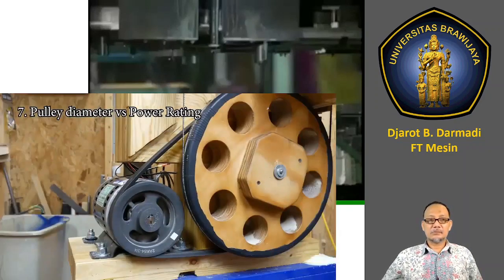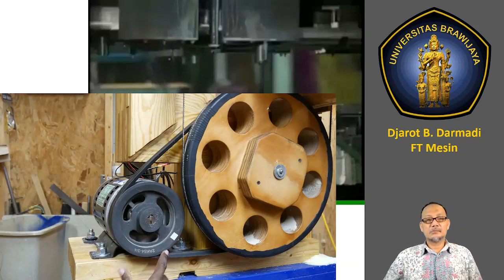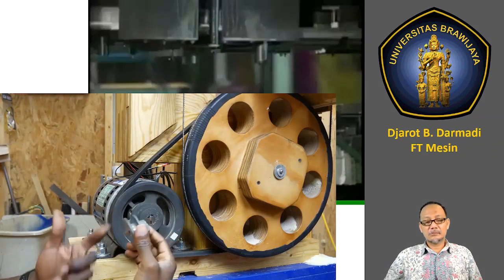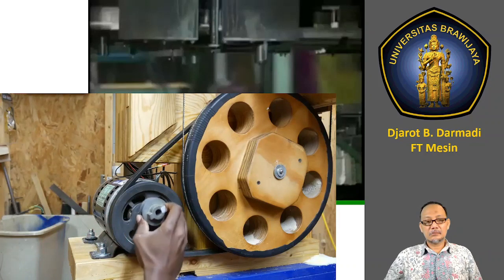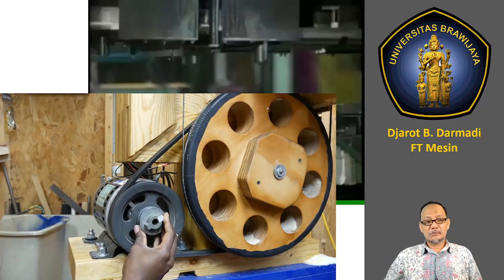Alright guys, I've got one more tip for you, and that relates again to the size of your pulley. You can look at my setup here and you say, well, Jeremy, you've got almost a 7-inch diameter pulley here, 6 3/4 actually, and then the 2 pulleys you made over here are 14.5. Why not use a small guy like this, maybe a double groove pulley, but a much smaller OD? Then you could save a lot of work, make that guy a lot smaller.